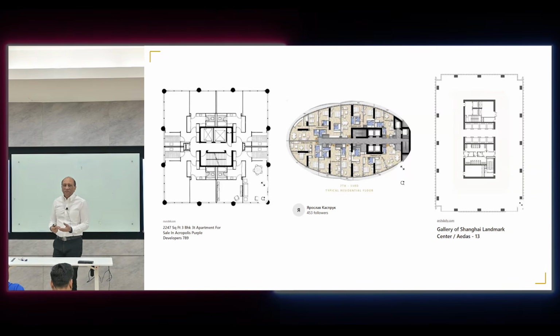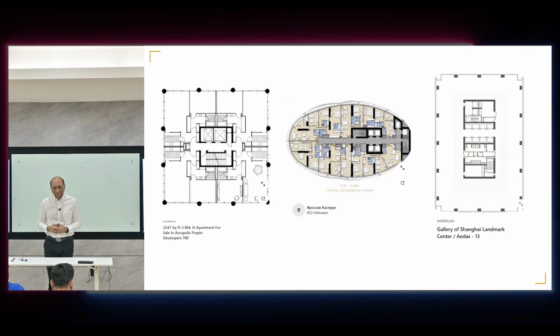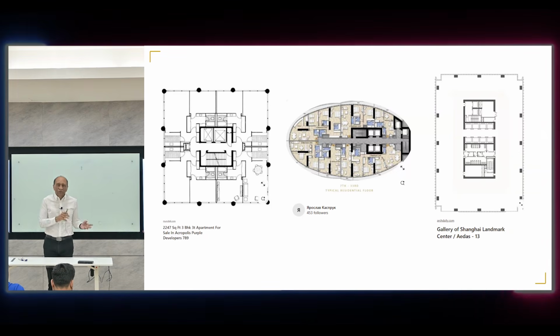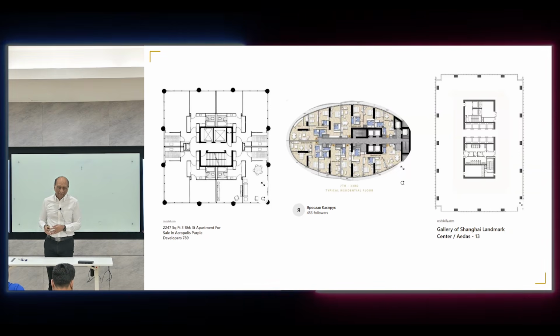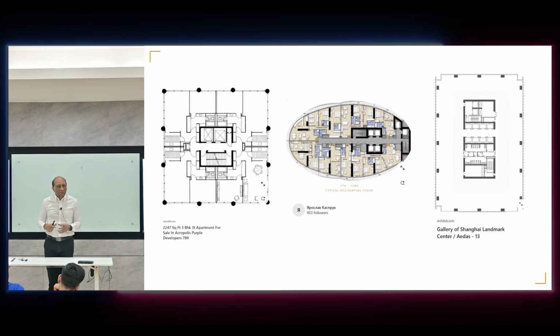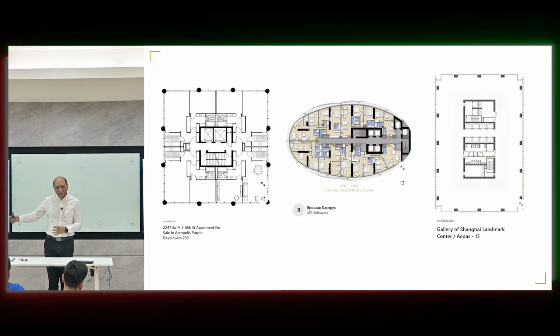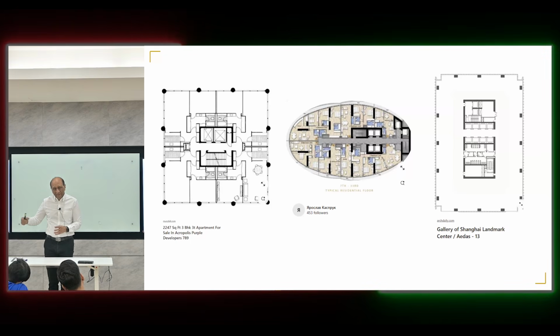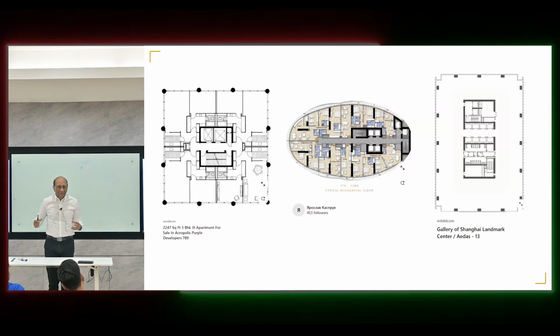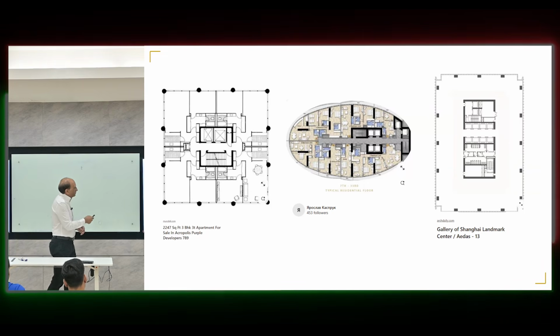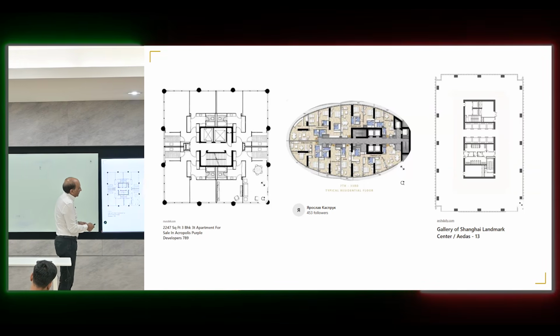Core is not sufficient typically in residential buildings, because residential buildings do not have all the services like a hotel has or an office building has. So that's why the cores generally for residential buildings are smaller than the cores in commercial or office buildings. Also, residential buildings are normally larger in size, so it's distributed. All of these will impact the design of the structure.